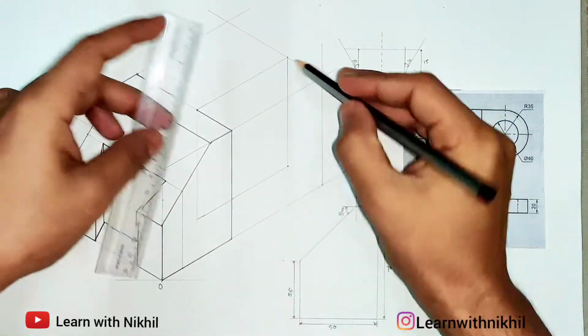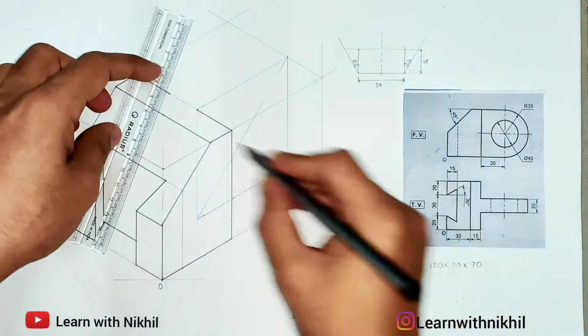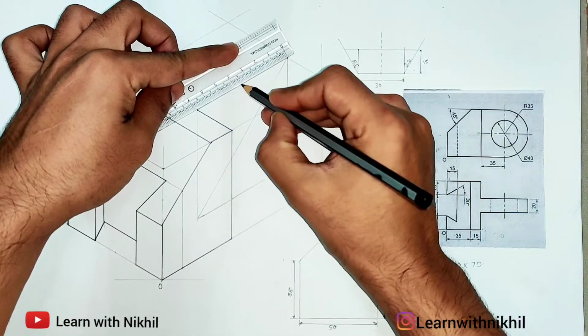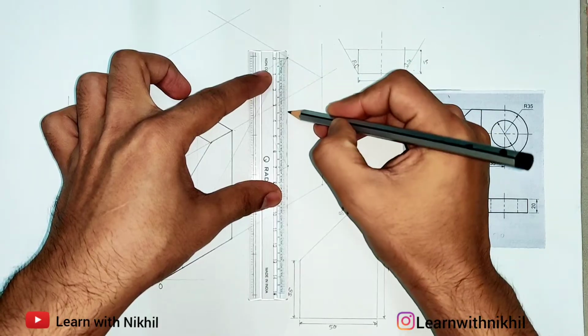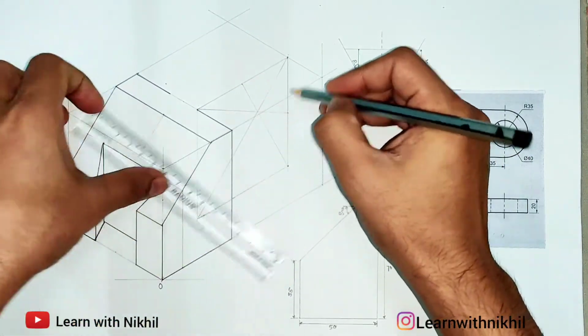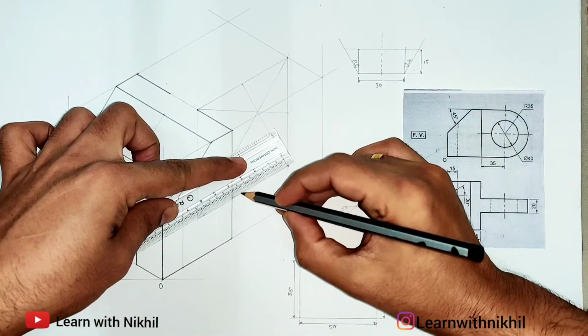Now the procedure of drawing the semicircle: join the longest diagonal. This is the longest diagonal. Then from the shorter diagonal, joining at the opposite ends at the center point. So marking the center point from here, join from here, join at the center point. Now here also we have to join at the center point, but I'll just mark the point.